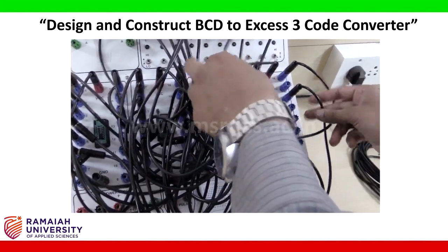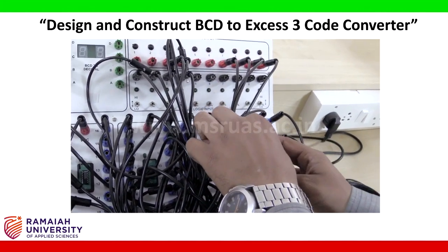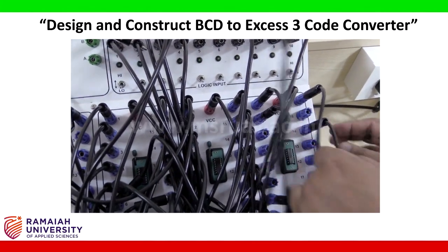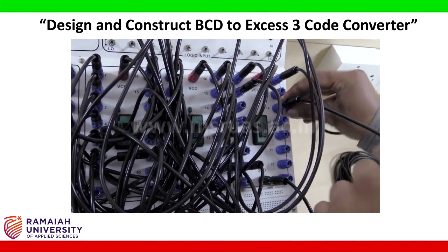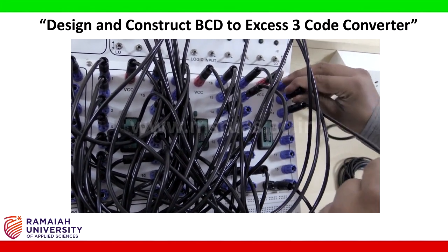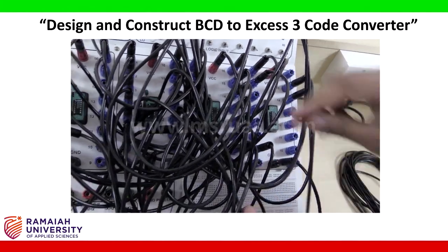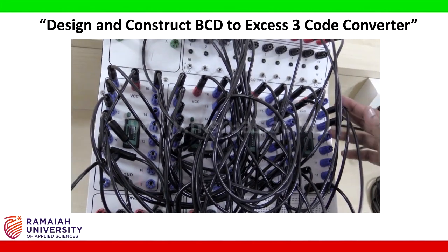It has 3 inputs, pin number 1, pin number 2 and pin number 13. 13 should be here, and pin number 12 is the output. It is connected to 10 of the OR gate and it is connected here. So this completes the circuit connections.